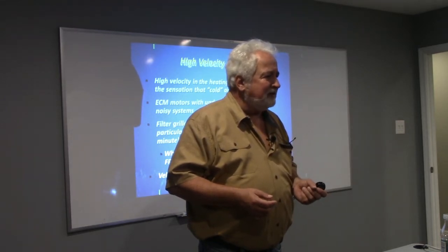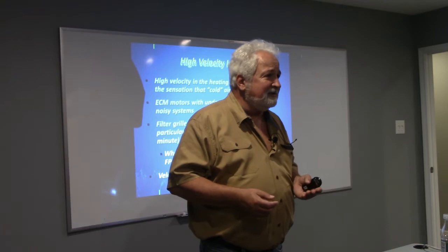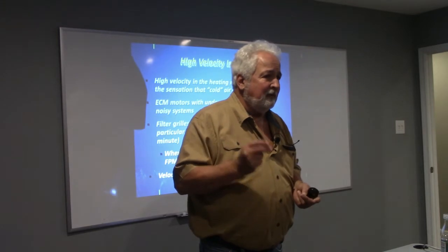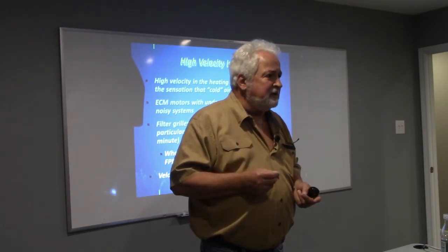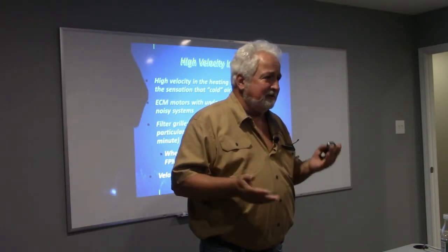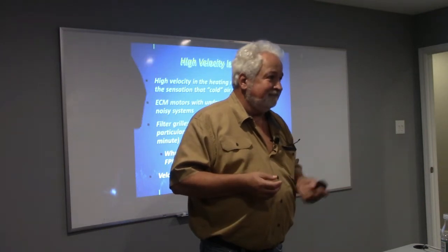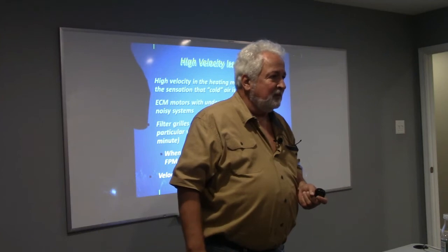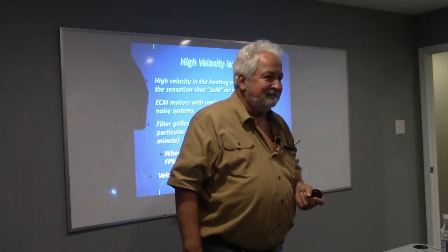Yeah. It takes about, what, 7 seconds, Mike? Is that what you said? About 7 seconds for you guys to take that liquid refrigerant and destroy a compressor. I heard it go pow, and then my pressure's equalized. Yeah. Sounds like rocks in there. Oh, there's the rocks. There's the gravel. You know where your rocks are now?